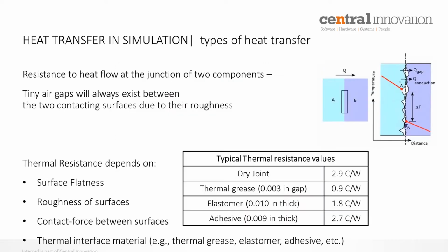So looking firstly at conduction. When we create a SolidWorks model and we touch two objects together, as we can see in this first screen here, they are perfectly touching, and our equation for conduction holds true, and the heat will perfectly conduct based on the temperature differences between them.